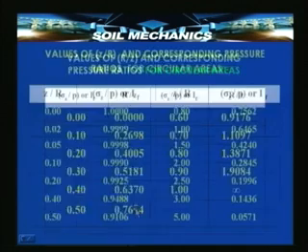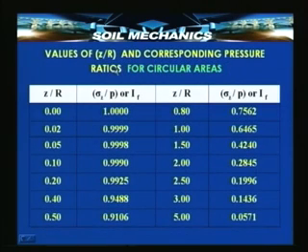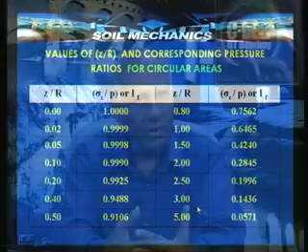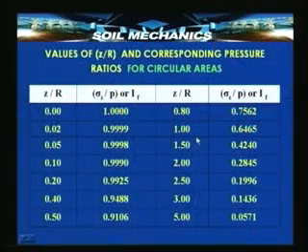It is the former table which is now useful for calculating stresses below a circular area. The range here is 0 to 5, which means that if in any given problem the depth is such that the ratio depth by radius of the circular loaded area is more than 5, then rather than using this table, we shall have to use the formula directly.